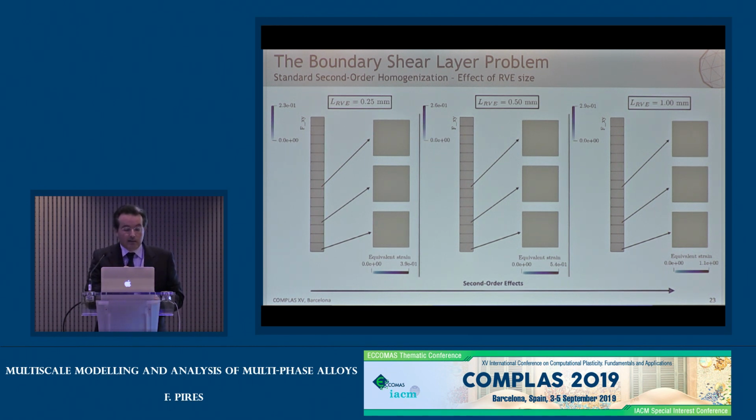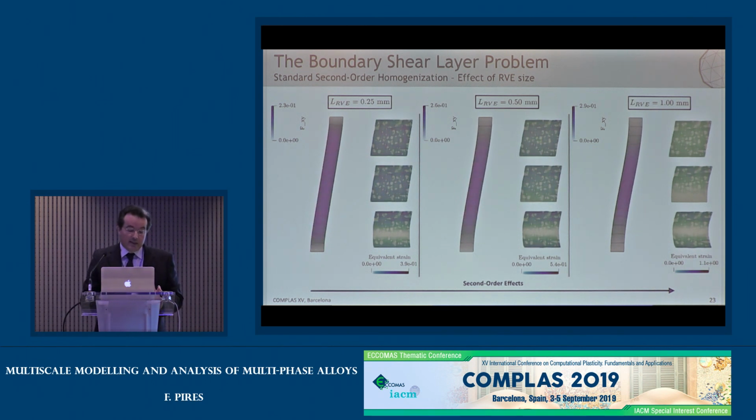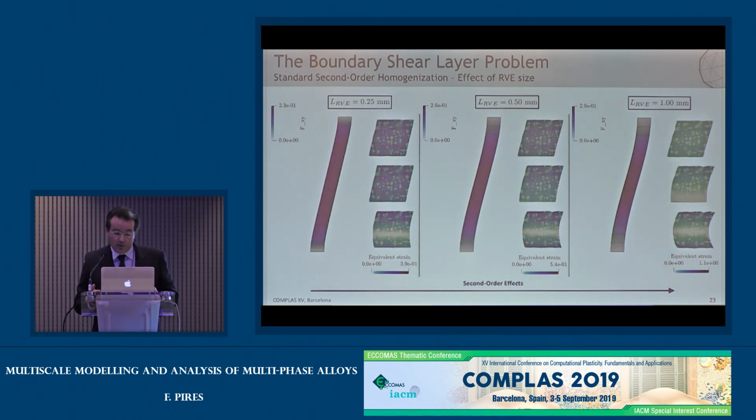I've again scaled the sizes to look the same. They are not the same, they are just scaled for visualization purposes. And I'll show, as the deformation evolves, what happens for 3 elements within the stripe. What we can see is that the first case is almost the first order formulation, so we don't really have quadratic displacements. It's almost a linear deformation, and as we increase the size of the RVE, you can see, especially on the bottom RVE, that the quadratic displacement becomes quite visible.